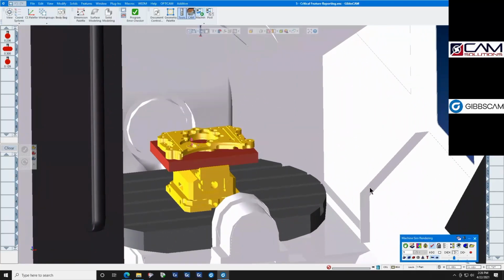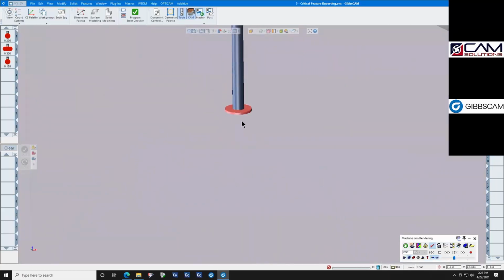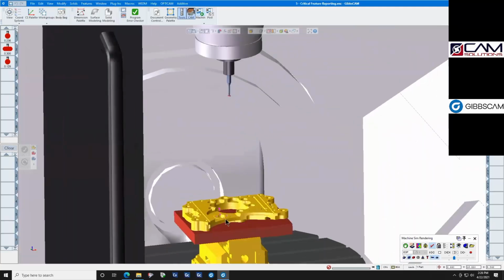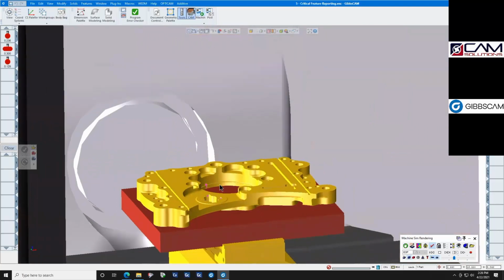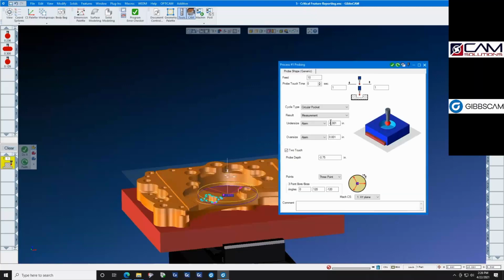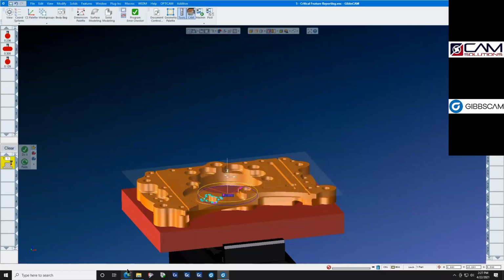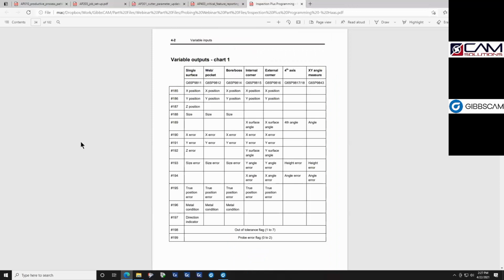That critical bore in the middle, and did you see that? We have support for a disc probe, and that disc probe did go down inside of here and measure that critical surface inside of that slot. Each one of those was output to a register in your machine because we said, just measure it and output the measurements inside of your machine. Now the question is, where does that data go in my machine? How do you know where the data goes?